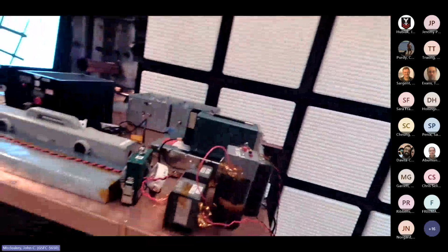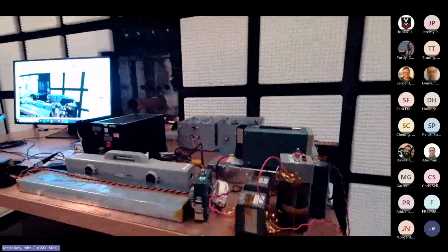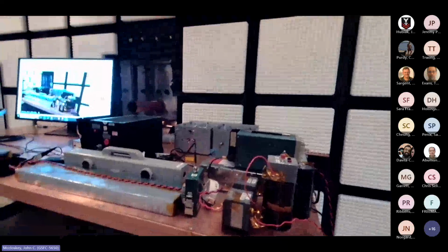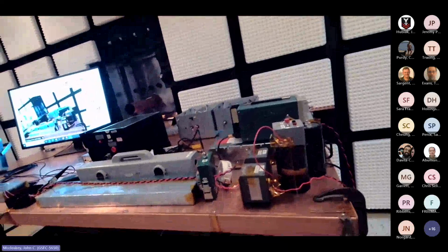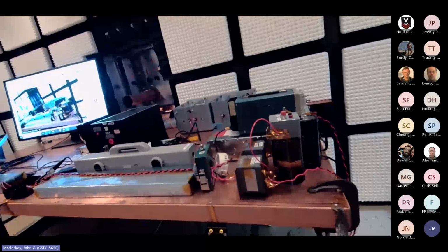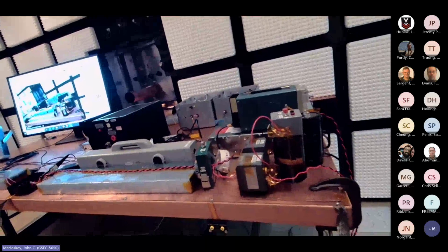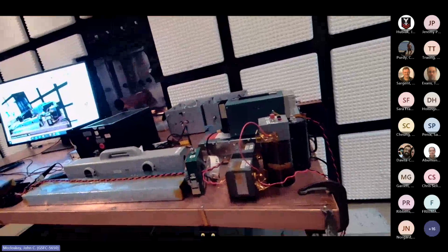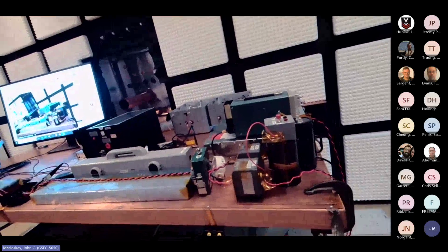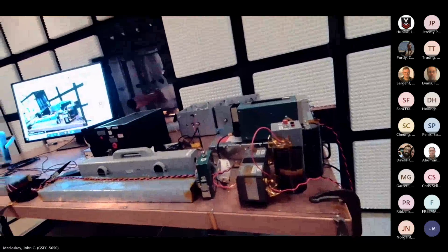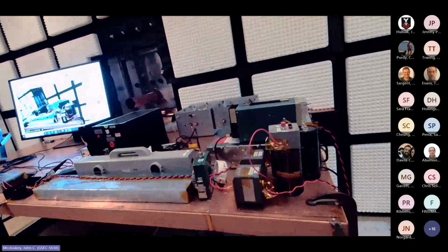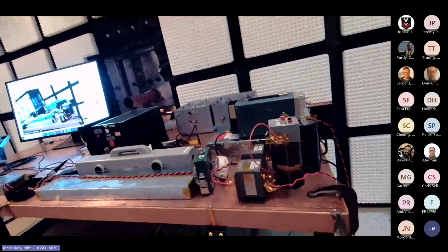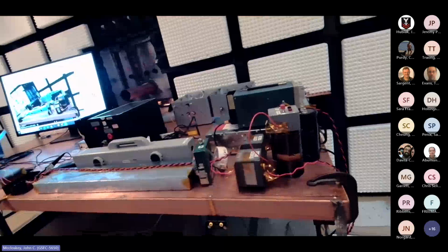So when we're on a spacecraft, we're generally running a dedicated return wire to each individual load. So our inductance per unit length is much lower in a configuration like that. Moreover, we generally run those dedicated wires from the load all the way back to the distribution point, or ideally as close to the battery as we can get it. So the LISN or any of your impedance networks really should be representing that common source impedance, not the total harness impedance out to your load.